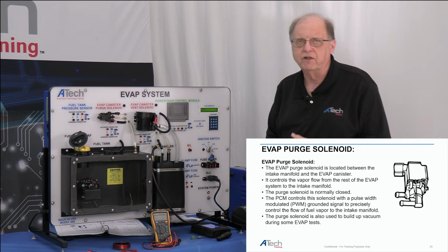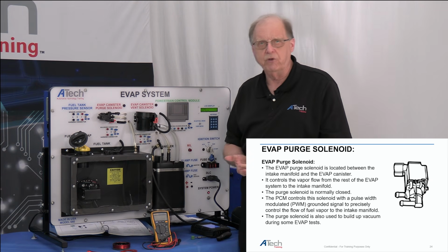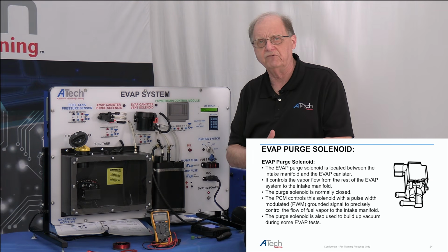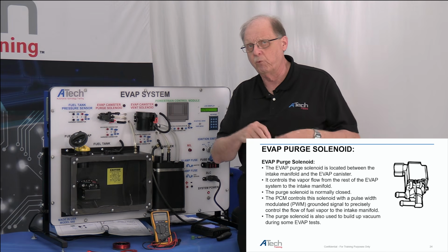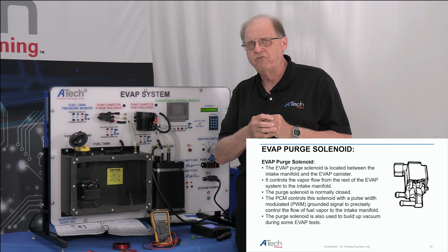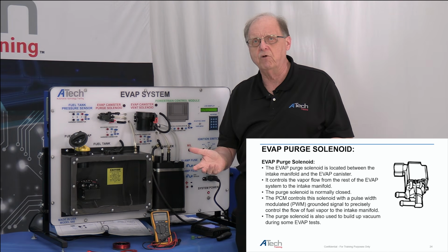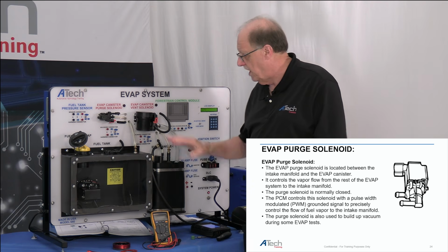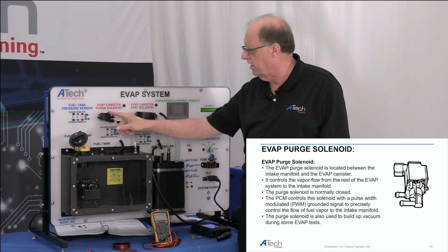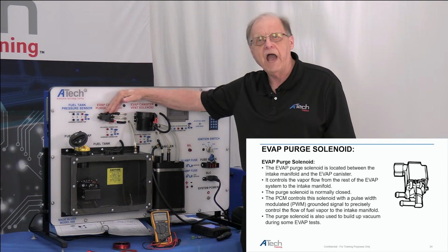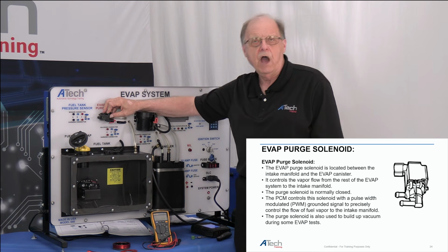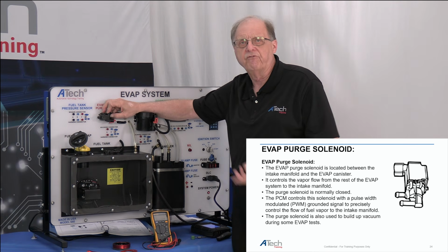Pulse width modulated. These are not on all the time like the older systems were. These are pulse width modulated. Remember the earlier systems were thermal switches, whatever, and they just turned on, they stayed on, they purged most of the time. These are duty cycled. So if I was looking at it, I would have a duty cycle here. I can use my multimeter, I can use my lab scope, I can check this for a duty cycle.